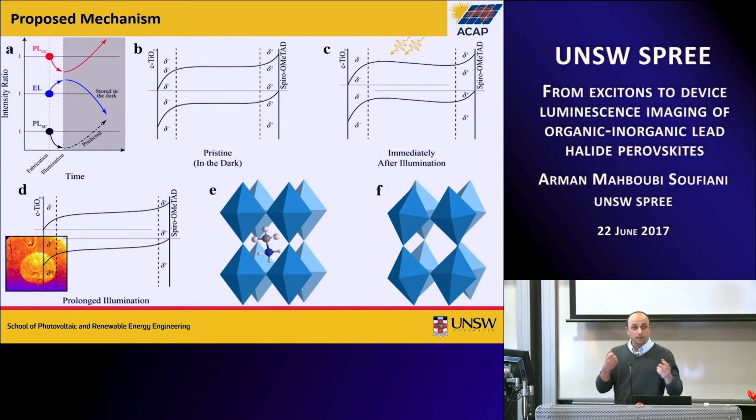And also the iodine defects can move around. That breaks the bonds. So I believe that when you do the prolonged illumination, the ions move away from the contact, and then when you rest the device, they want to recover, and all of these back and forth processes weaken the structure. And when you do, for instance, TEM, it separates at that interface, and over time actually you lose the contact.